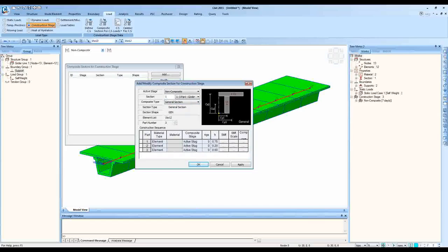And for part 1, the material type can be either element or material, and you can pick the girder material. Let me come back to what the material and element is once again, but give me 1 second. Let me first choose the material for different parts. So this part 1, 2, 3 is referring to girder, cover plate, and the deck portion 1 by 1.